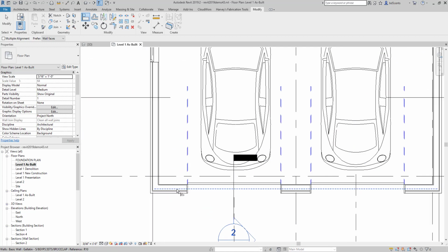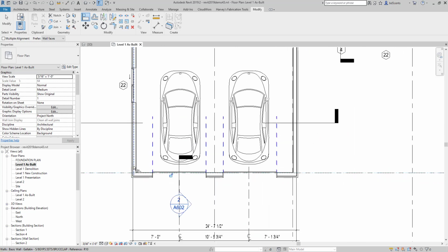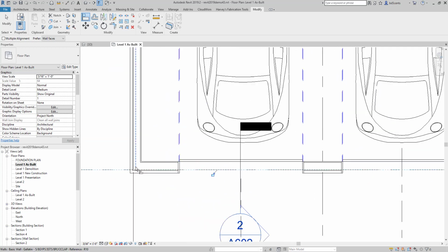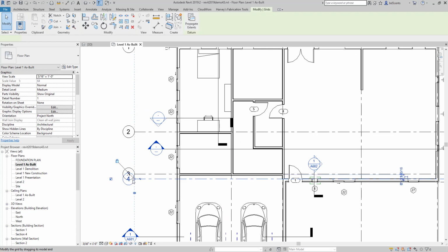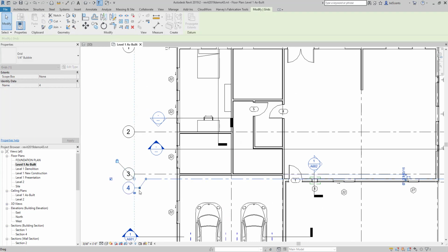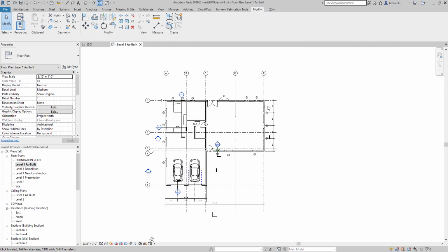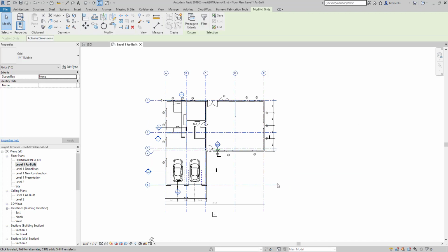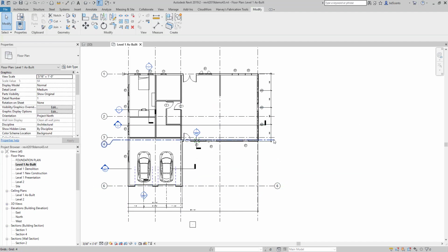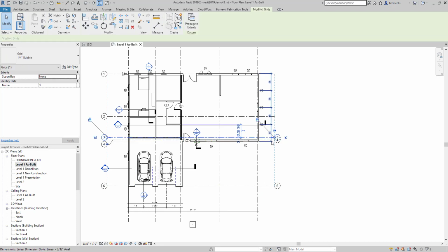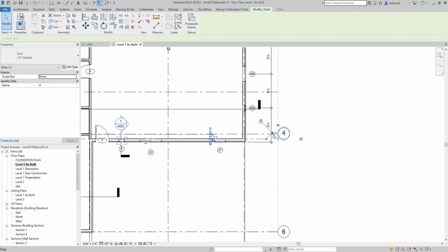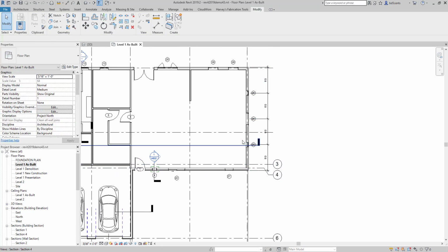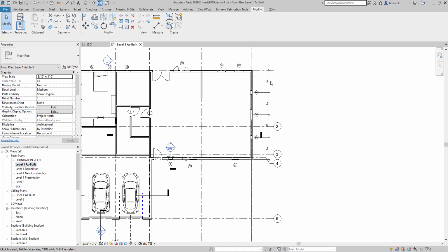Continue on. And then number 6, inside framing. We probably want to go to outside on this one just because we're at the end. And then I can actually break this and have it kind of below. And then I can also select these and turn the grid lines on. If I right click, select all instances in entire project, it doesn't work. You have to do it one by one, but you're just going to go through and check these. Same thing, just break this, have it fall down below so you can read it. Grid line on. I'm just turning on all the grid lines, grid bubbles.